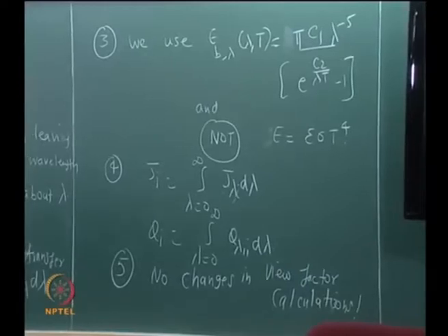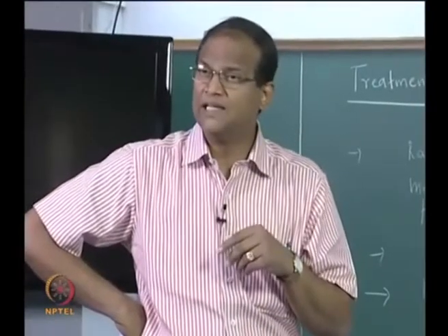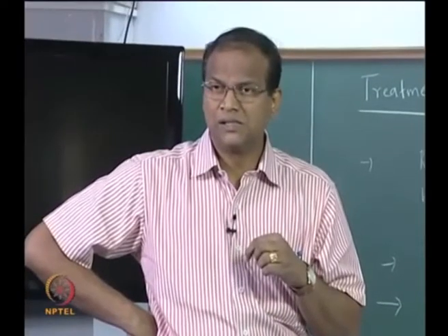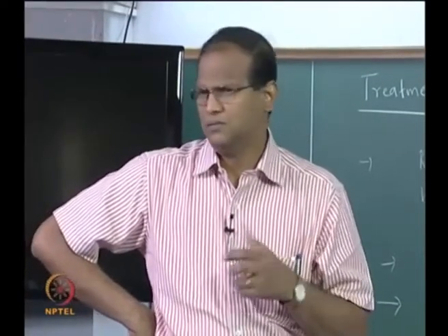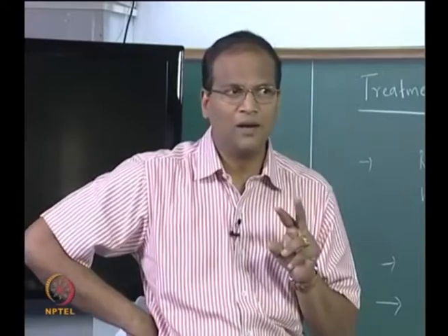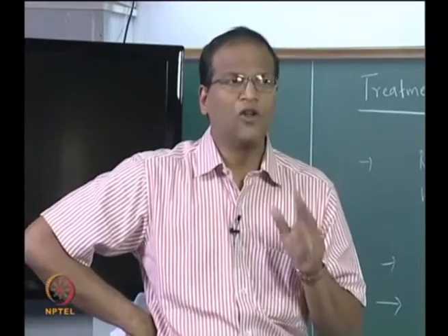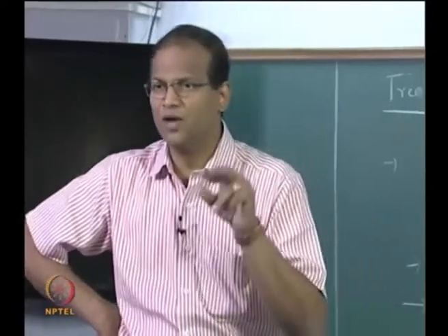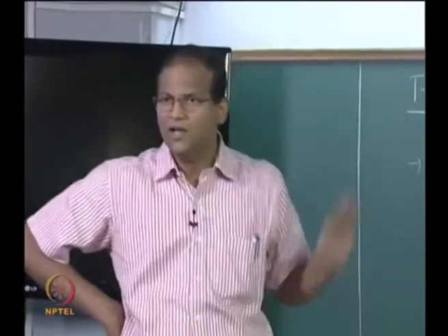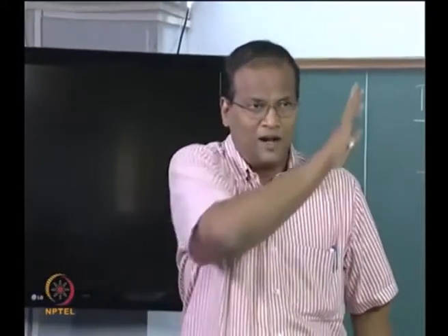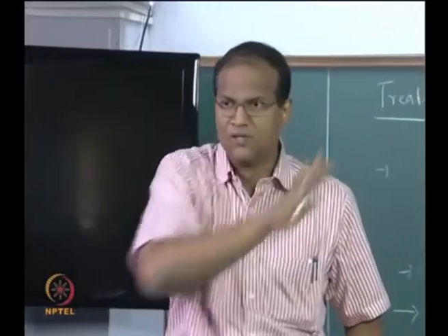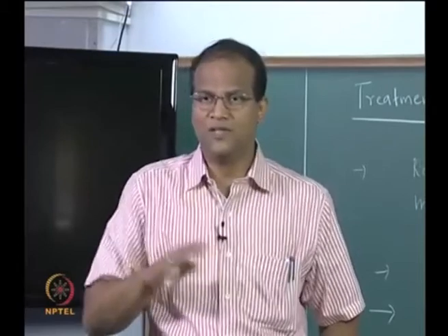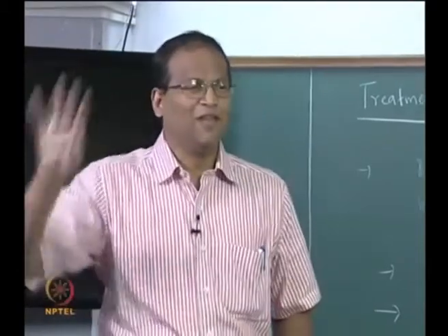So how do you get the reflectivity? It is spectrally dependent. Therefore you have to invoke Kirchhoff's law. To get the reflectivity you have to invoke Kirchhoff's law and say that alpha lambda is equal to epsilon lambda. So this completes the formulation, this gives you the broad framework after going through these important rules. This is like COT or prerequisites. Once we have all this, then we write the formulation.